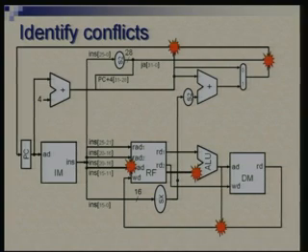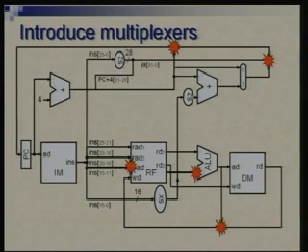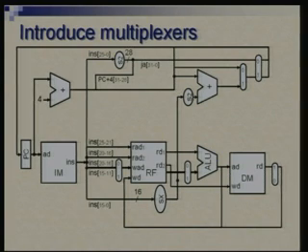So, what do we do for these? From the other design, we can actually get an idea that we need multiplexers, and multiplexer will be driven by suitable control signals. So, we introduce multiplexer. Basically, we have to introduce multiplexer and also connect the signal appropriately. So, you would notice that except for one place I have put in the multiplexer. The fifth one, the point of conflict between non-branch and jump instruction and other instruction would get resolved automatically, because the multiplexer we have put for branch itself will take care of that, because it is a conditional branch.